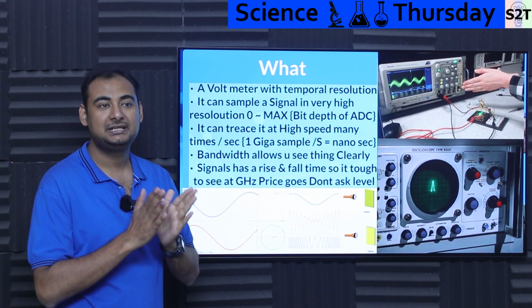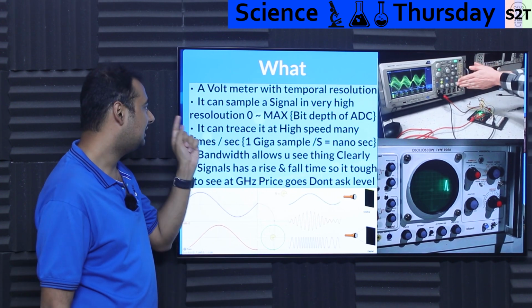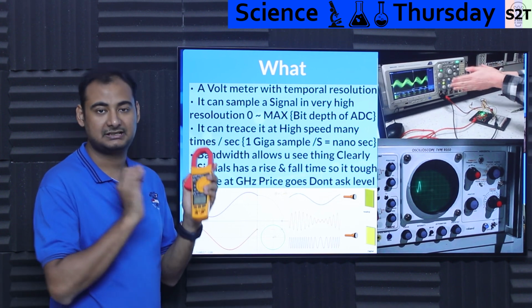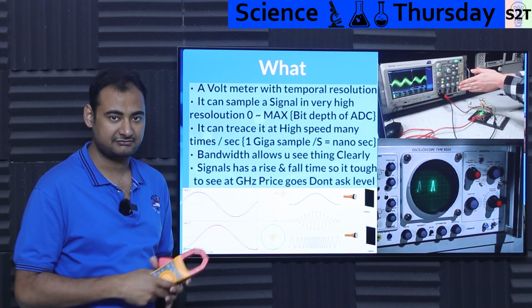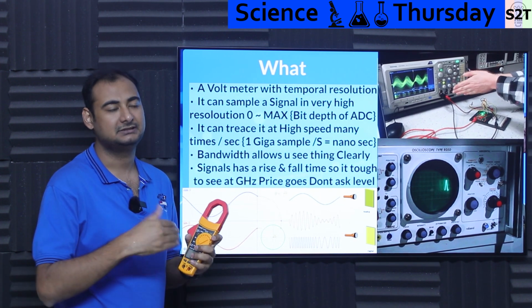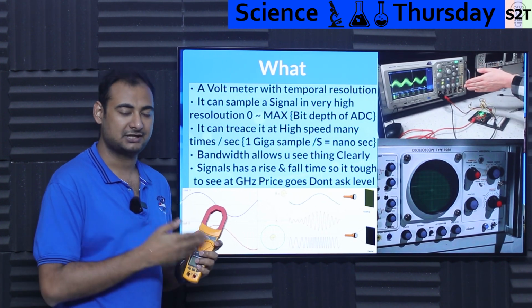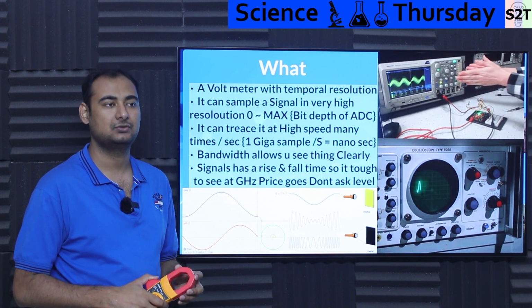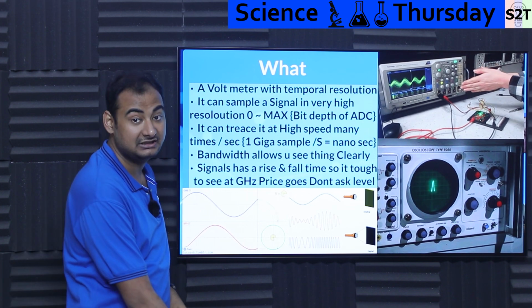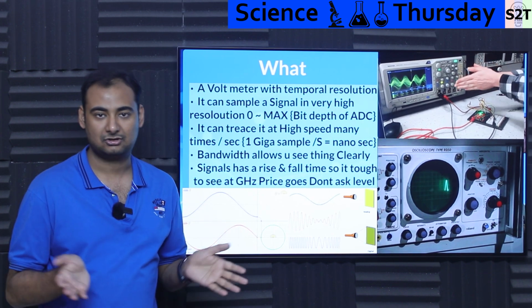To make this job easier, we start with a sampling system. Whenever you buy a meter, it will have a circuit that we call an analog to digital converter. You connect the probe, and the signal, the energy at the probe point, goes to the analog to digital converter, which is like, okay, this voltage level goes to this digital value. So we call it an analog to digital converter.